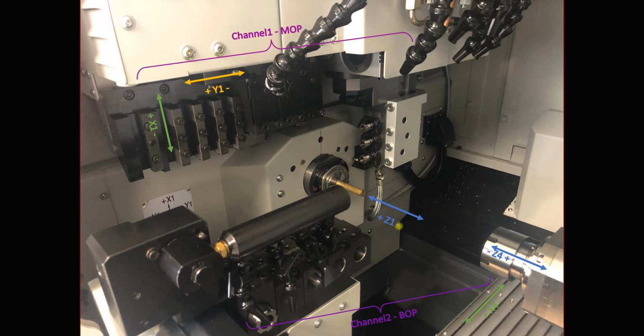Movement in minus direction in Z1 means withdrawing a bar in the machining area. In plus, this is retracting back. In Z4, direction in minus means approaching to a tool. This means that in a program we will use negative values in this operation when we would like to position in material. Also, it is necessary to add that both x-axes, X1 and X4, are by diameter. Positions in these axes are given by diameter.